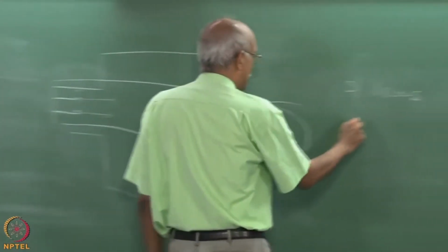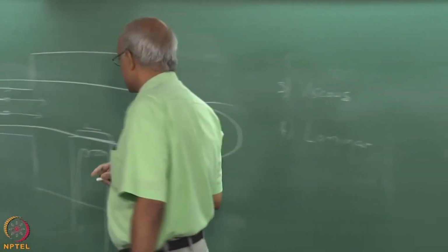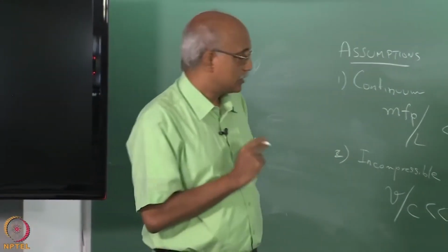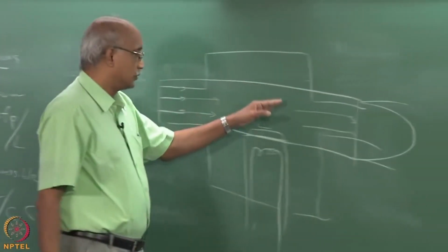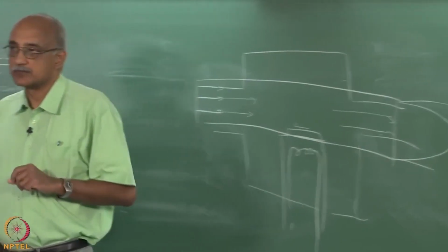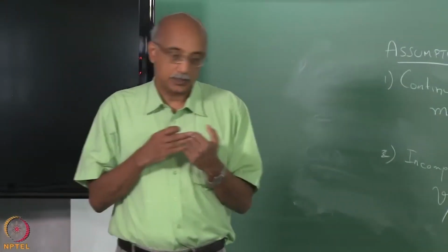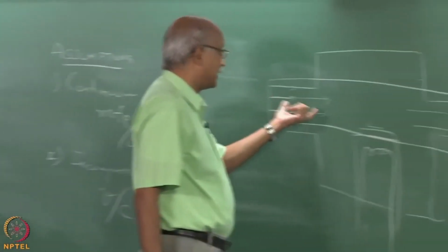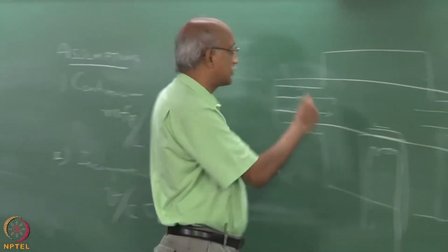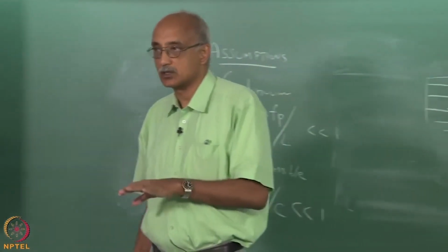Another assumption that we have mentioned even earlier is laminar. So, again the laminar flow is what gives you that parabolic configuration, but in terms of the surfaces that the fluid comes in contact with, what does that imply? What do we mean when we say laminar flow? Right. So, when we say laminar flow, the entering flow is at a uniform velocity of u infinity, and that velocity drops to 0 everywhere along the solid surfaces that the fluid comes in contact with.